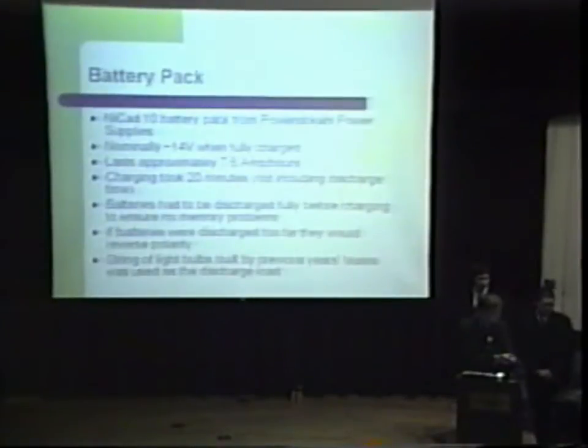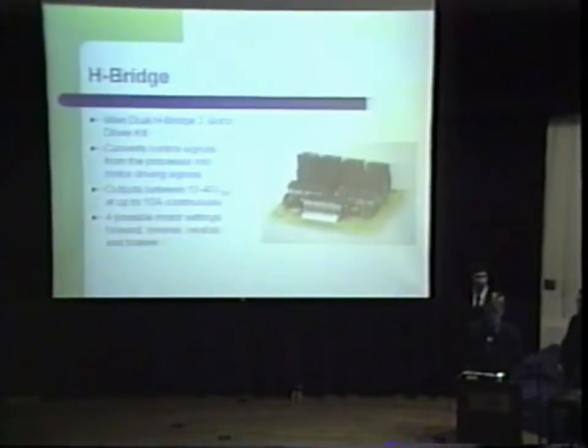The H-bridge we used was a Maxi dual H-bridge motor driver kit, and this was basically the circuit that converted the signals from the processor into usable signals that were sent directly from the battery to the motor to drive the motor, each one independently in either direction. And there were 4 possible motor settings: forward, reverse, braking, and neutral. And the outputs could be anywhere between 10 and 40 volts.